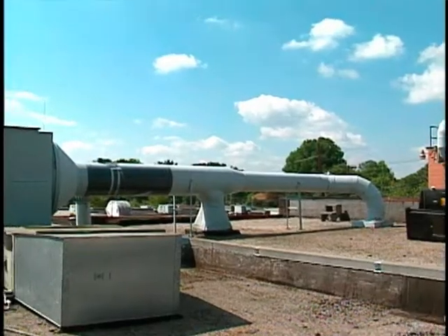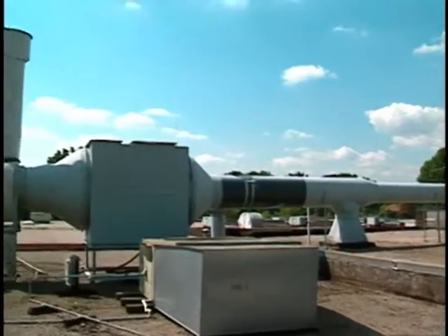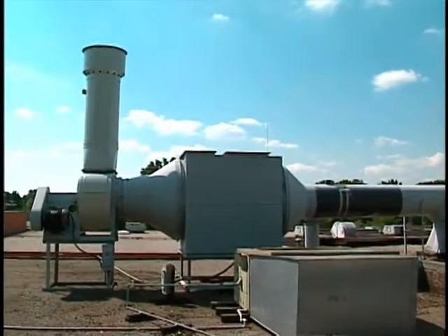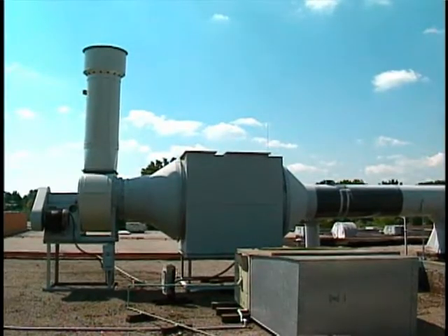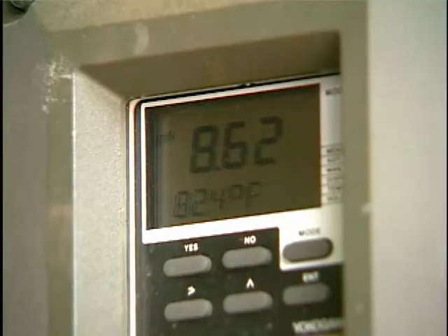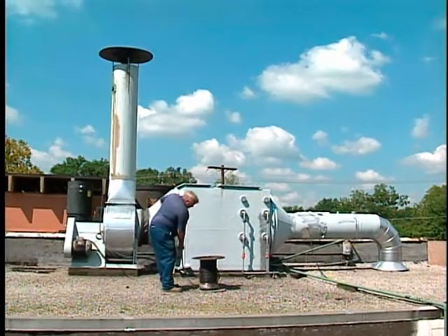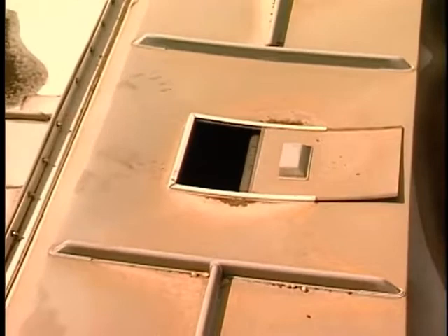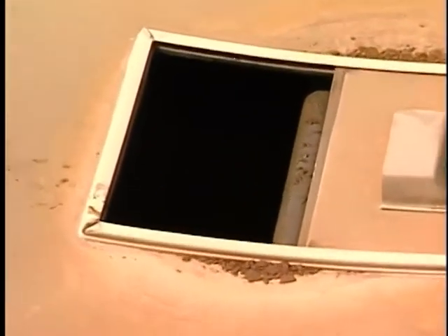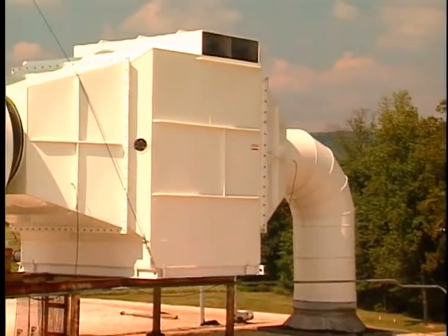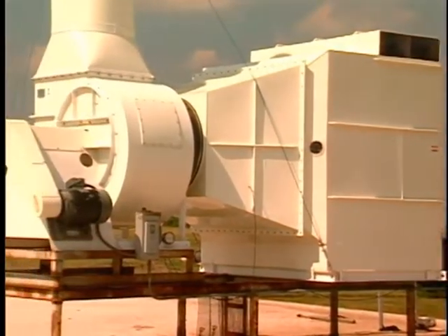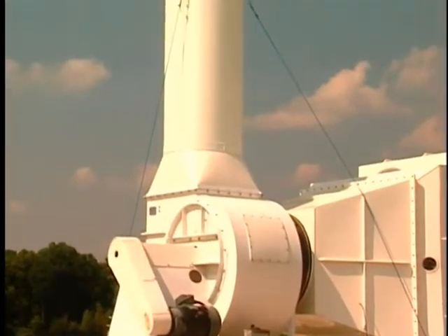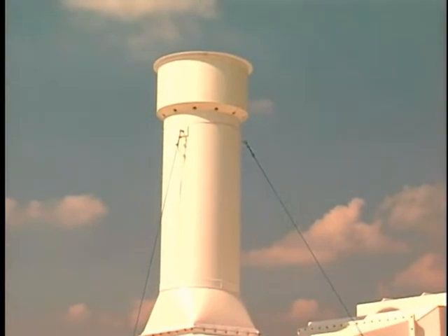Perhaps the best indicator of adequate gas-liquid contact is the difference in temperature between the inlet and outlet of the absorber. If that temperature difference has decreased, it is likely that the collection efficiency has also gone down. The liquid flow rate into the absorber is also important. If the flow rate is being monitored, the value during the inspection should be compared to the baseline or permit value. A decrease in the liquid flow rate without a proportional decrease in the gas flow rate will usually cause a decrease in the collection efficiency.